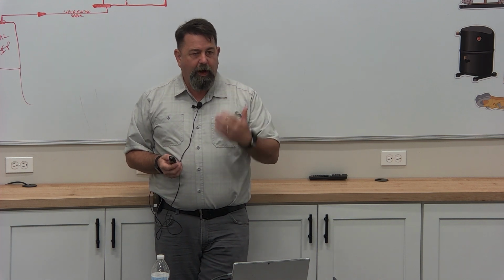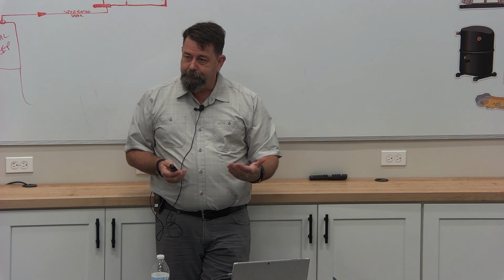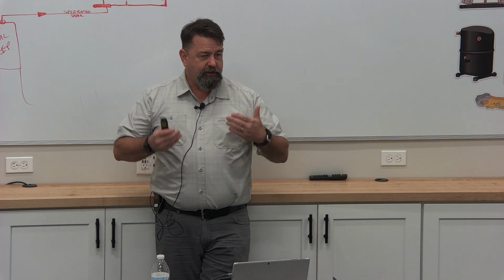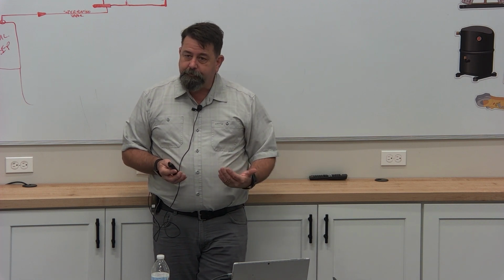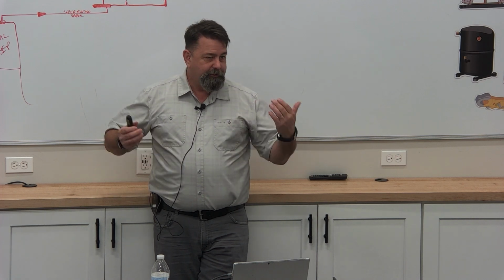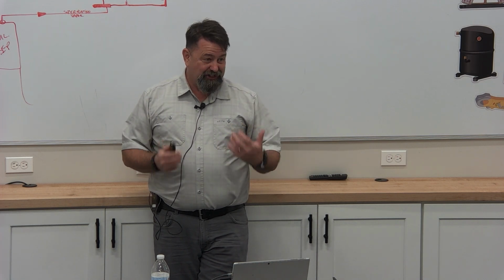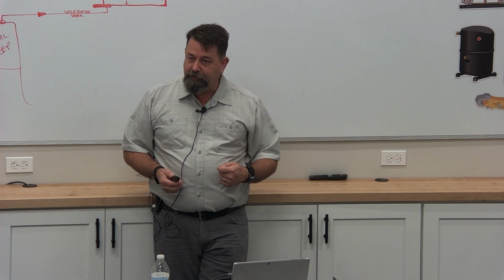Okay? So the way that I make the surface area of my heat exchanger bigger than just the copper tubes is I mount aluminum plates to it. I can use any conductive material. It doesn't have to be aluminum. We choose aluminum not because it's a really great thermal conductor, but because it's cheap and light, right? Copper would be better. Copper things would be way better. They'd exchange heat far better, it'd be stronger, more durable, but insanely expensive, and crazy heavy, right?